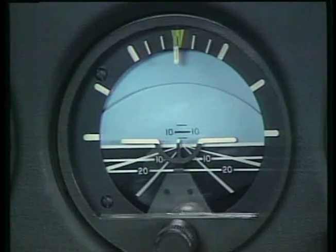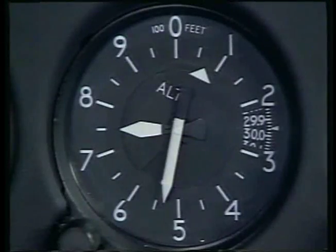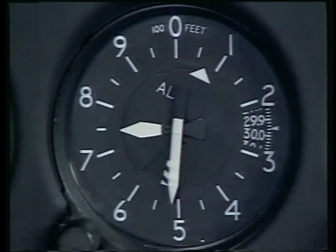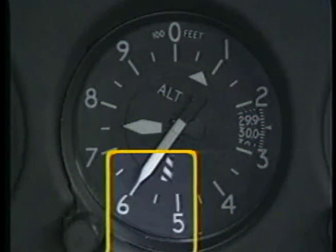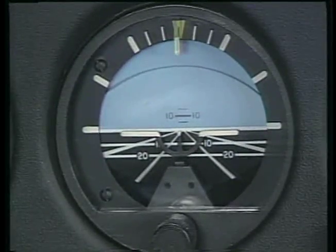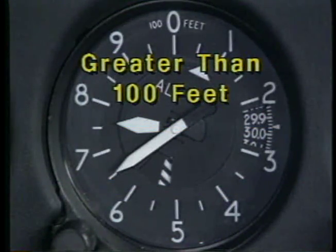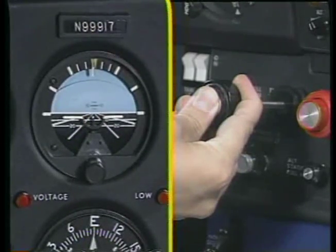You should make corrections by referring to the attitude indicator and monitoring the altimeter to complete the adjustment back to level flight. As a general rule, if the altitude deviation is less than 100 feet, you should correct the pitch attitude without changing power. When the deviation is greater than 100 feet, you should combine a pitch change with an appropriate power adjustment.